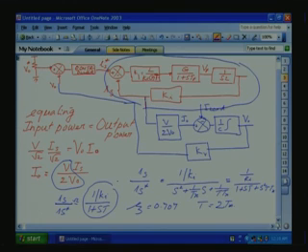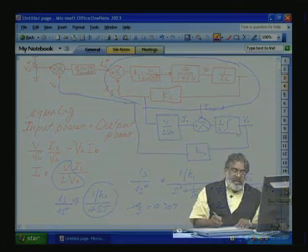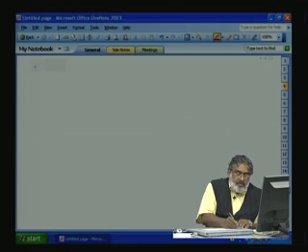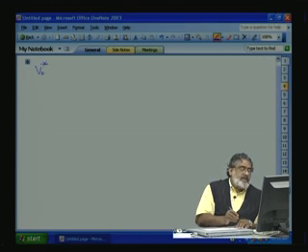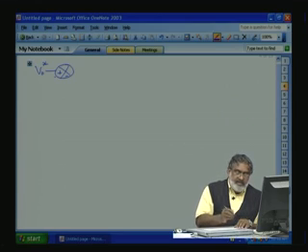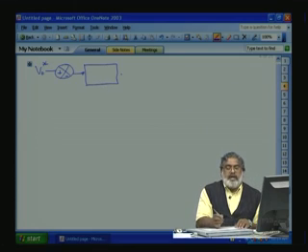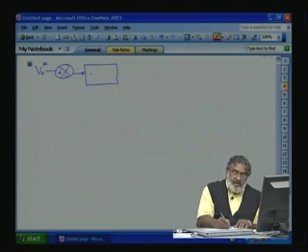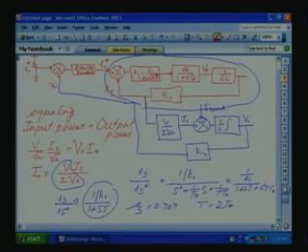Okay, the block diagram of our voltage loop. Let's go to the next page. You have V0 star, our reference, plus minus, then our controller. Let us again take, for good dynamic response, the PI controller. Here at this point we get the I0.